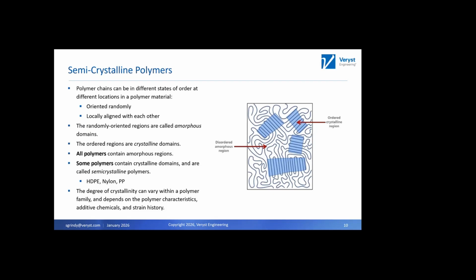There are, I would say, essentially no polymers that are 100% crystalline. Perhaps there's an edge case out there. Maybe I'll learn about it sometime soon. But for practical engineering polymers, they're always semi-crystalline. That crystallinity can be as low as 10%, and can go up to 60, maybe even 70% or something like that, just to give a range there.